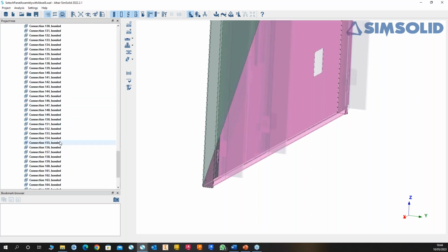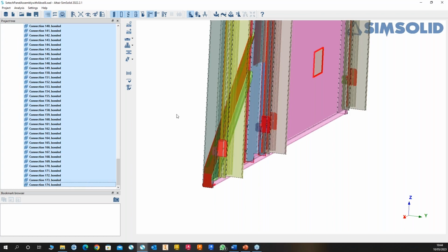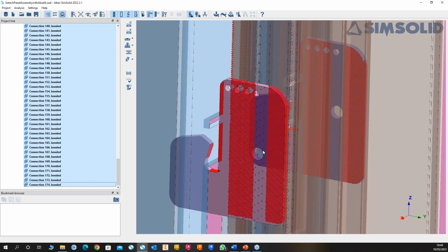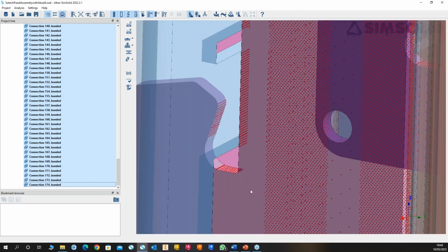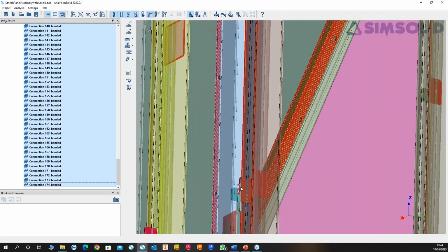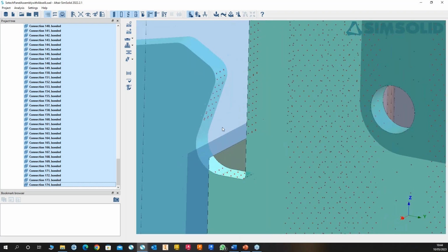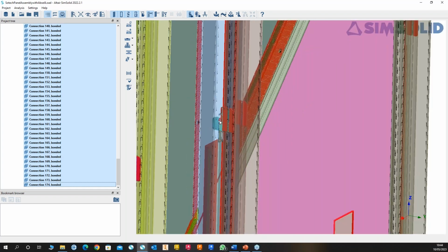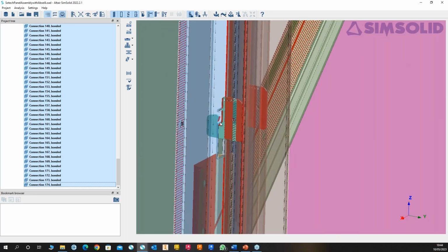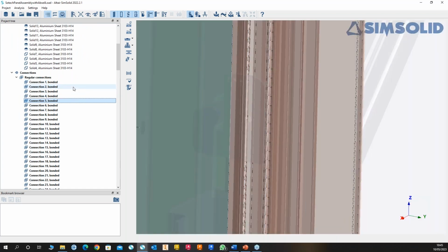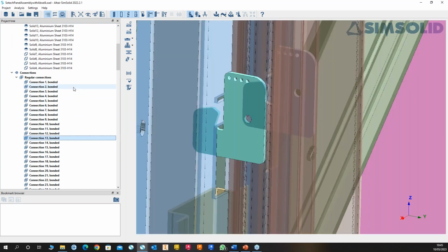So I'm going to select all these contacts again, just to show that it has picked up that contact there. See the one with the gap, it's selected there, so it's recognized that, and it's also recognized this one, which you could have as separating and closing contacts. It'll do no harm, but I tend to just run this without them. So we've got a few options. We could go manually, look for these contacts and change them to whatever we need. I'm going to scroll down here until I find that one contact.